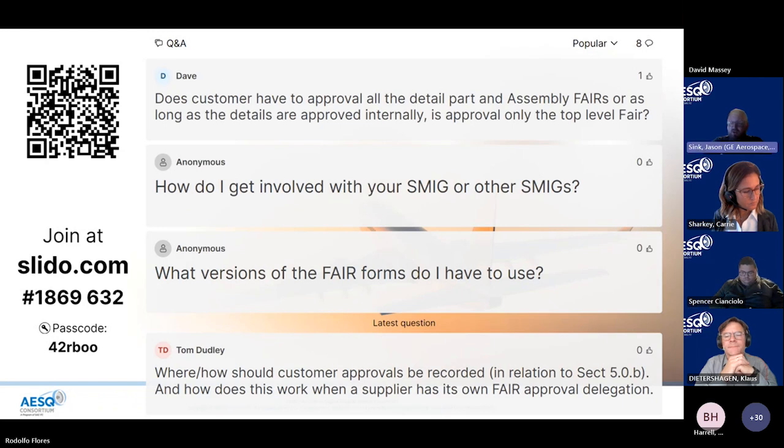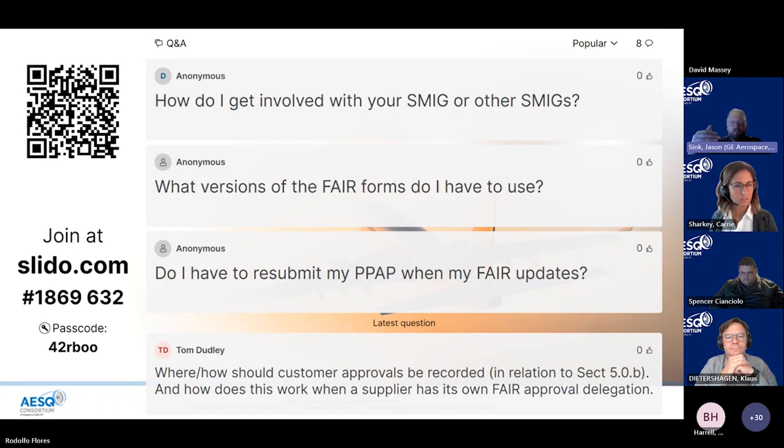That is also a very good question, and it's going to be dependent upon a few things in my mind. First being, is this supplier design? Because in many cases, I see OEMs allow supplier design with multiple components to have their first article inspections internally approved, and then whatever the OEM is ordering from the supplier only has an FAI and has that approved.